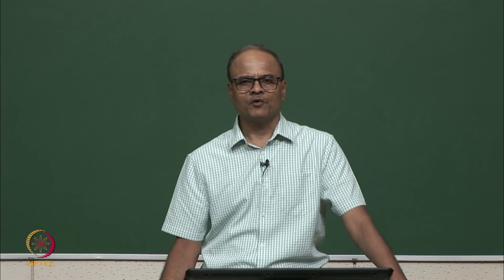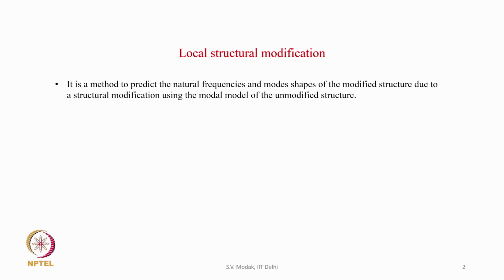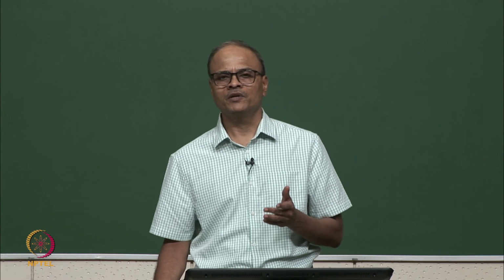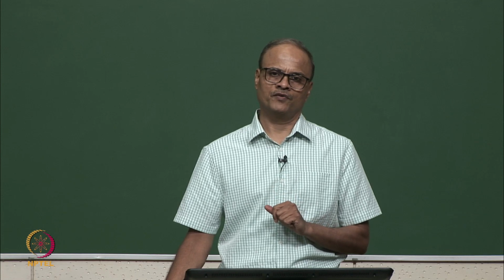So what is local structural modification? Local structural modification is a method to predict the natural frequencies and mode shapes of the modified structure due to a structural modification using the model of the unmodified structure. If there is a structure and we want to know what the new dynamic characteristics would be if any structural modification is introduced, then this method enables us to predict them based on the model of the unmodified structure. This is the basic idea behind the local structural modification method.